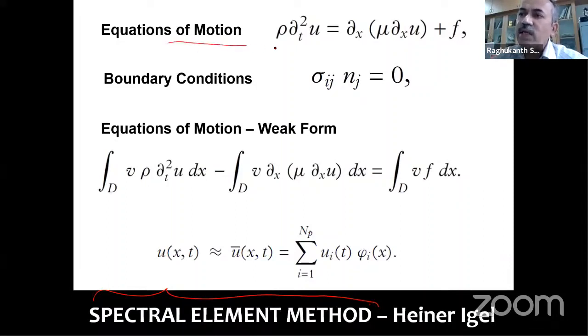These are the basic equations of motion in continuum mechanics. You would have studied in your BTech simple bending theory and other things, where you write in terms of bending moments and shear force. But if you write the equation directly in terms of stresses or displacement, this is the overall equation. I'm showing you the displacement equations of equilibrium. And we have the boundary conditions also. Generally the surface is stress-free, and you have to use absorbing boundary conditions at the edges. The boundary conditions are very well known. Using these boundary conditions you can solve any problem; you can model a beam, you can model anything. Now we use these equations to model the Ganga Basin itself.